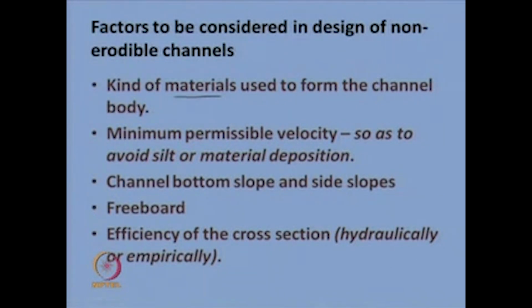That is quite essential, because it is the material that determines the roughness of the channel, right. You are quite aware now that different materials have different roughness coefficients, and once the roughness coefficient changes, the flow or the discharge changes quite immensely. So, it is one of the most important aspects while designing non-erodible channels.